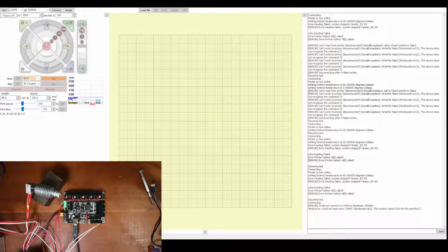So we know we didn't change this. I don't think that's the issue. So let's jump to the next set of stuff. So we've got the E0, which is extruder 0, auto fan. Then we have PB3. So what is PB3? So if we go over here and we click on this, we got to look for PB3. So PB3 is this pin right here. So that's odd. So let's think about this for a second. We're saying the auto fan is on HE0 for PB3.